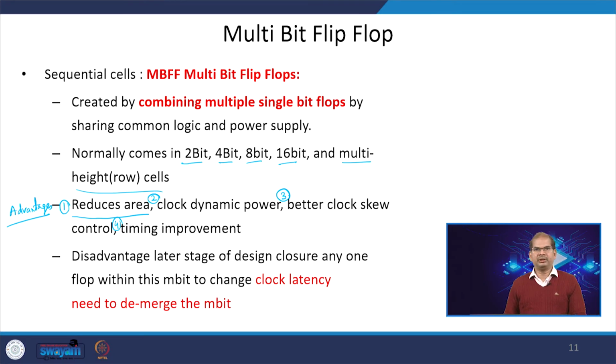And the disadvantage of the multi-bit flip-flop is that whenever you have a design issue because of the timing of any one of the flip-flops inside the multi-bit flip-flop, we need to break that multi-bit flip-flop and create single bit flip-flops again to meet the timing.